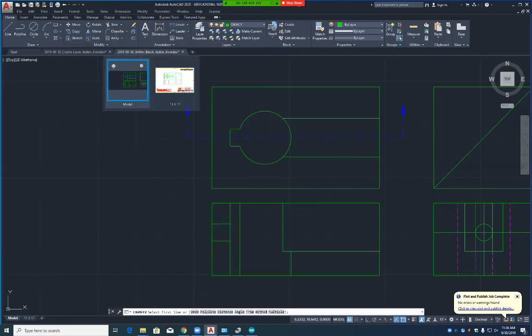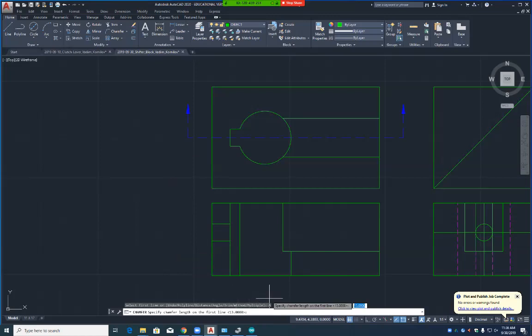And then we'll add those chamfer corners as hidden lines again. Will we add those chamfers as hidden lines again? No, there's no hidden lines in a section view. No hidden lines, period. If you put it in there, it's wrong, because you don't want to see it. You just want to see what you physically see when you cut that in half. Just what you see only.